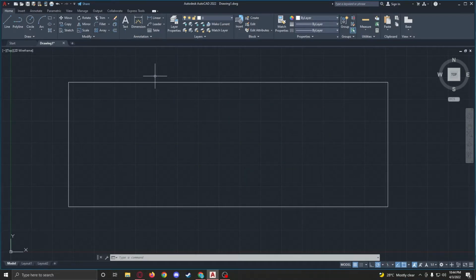What the explode command is going to do is take the object that we created, this rectangular block. This block is 4 individual lines, but they're joined together as a polyline. So when I do the explode command, I select the object, and it doesn't know that I'm done selecting, so I'll press enter to tell AutoCAD I'm done, and that's it.